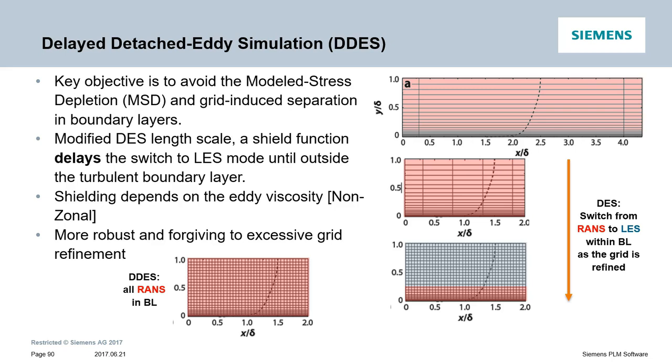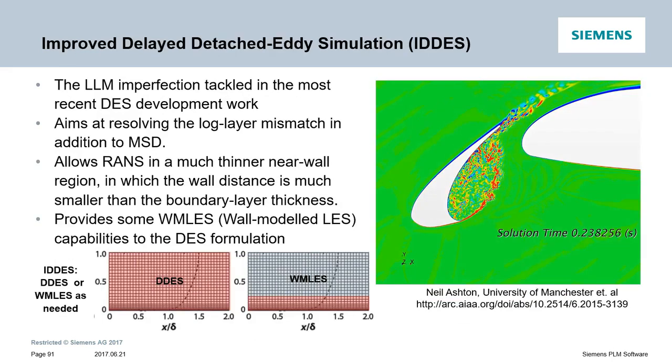So following Menter's idea, Spalart later proposed several modifications to the original DES, including shielding functions which depend only on the eddy viscosity and the wall distance. So it therefore in principle can be applied to any eddy viscosity based DES model. And there might be situations when I want this switch to happen in boundary layer. When would that be needed?